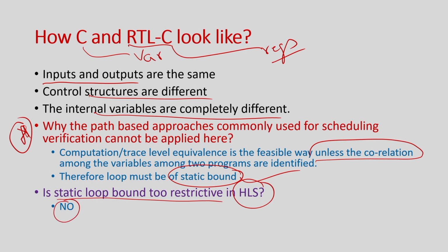If you remember, in high level synthesis we do not support dynamic memory allocation. So, malloc, calloc, those are not allowed. So, the array is basically a fixed bound. You cannot just malloc during the program execution, because dynamic memory allocation is not supported by high level synthesis. So, it means that the arrays are of static bound or fixed size.